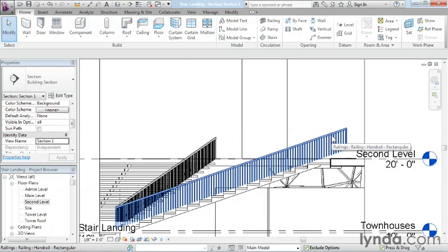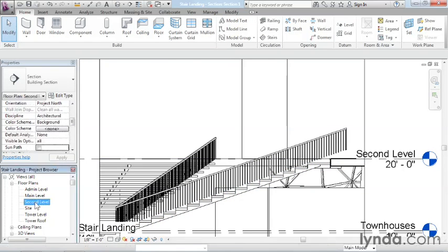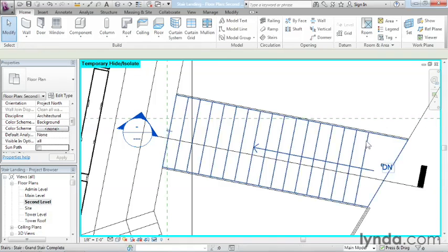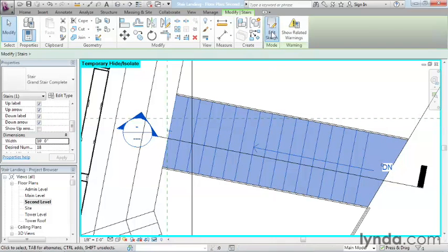And you see what's happening to the railing here, how it's kind of shooting off and continuing that same angle there. What I've actually done by angling that tread is made a really long tread, but Revit didn't have any way to calculate that, so it kind of just kept going with the same slope of the existing stair. What I need to do is go back to the stair, click on it, edit the sketch.